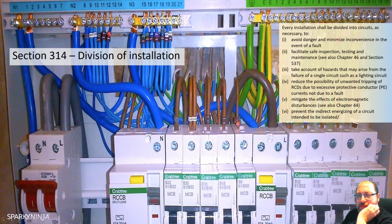These are the kind of things that we're saying. You should ensure that you have switchgear, control gear and isolators as local to the point of isolation as possible to facilitate safe inspection, testing and maintenance. If you require a larger part of the installation to be isolated, then sometimes that can be considered as not reasonably practicable, or sometimes the work will be planned at a much less frequent interval, which again is not suitable for the life of the electrical installation.